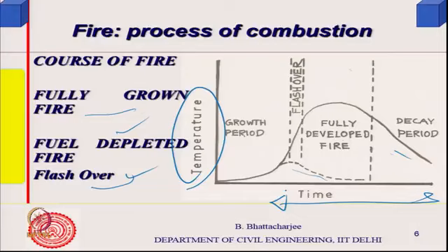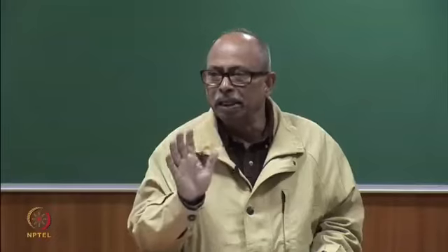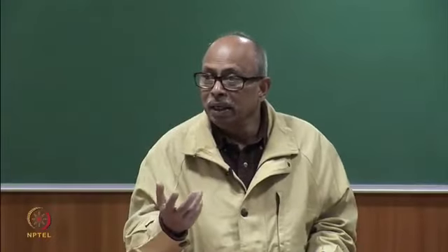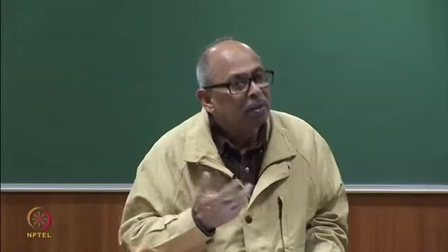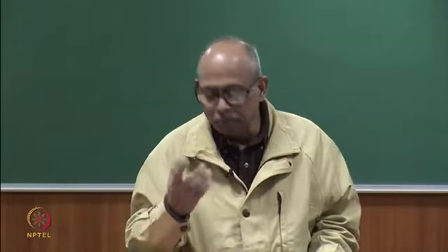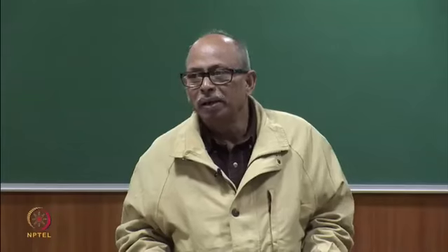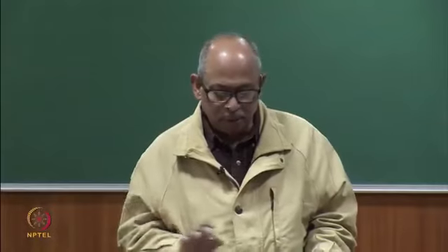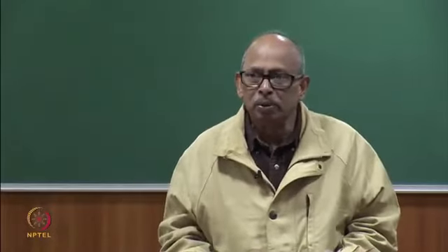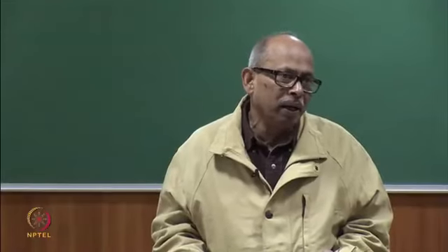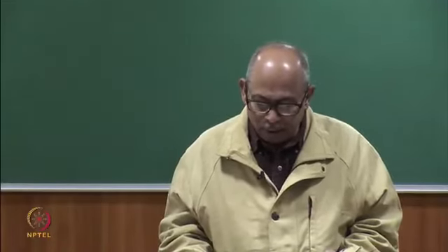Supposing I have a lot of fuel, then the steady period would be longer. I am talking of fuel density, with the room volume remaining the same. If you have a higher fuel density, then it would require a longer time to burn out. So temperature and time, these are the two issues. So fires are defined by the time temperature curve. We will come back to this again.